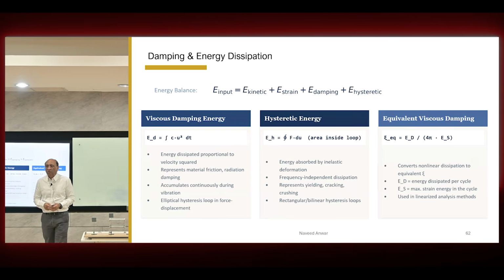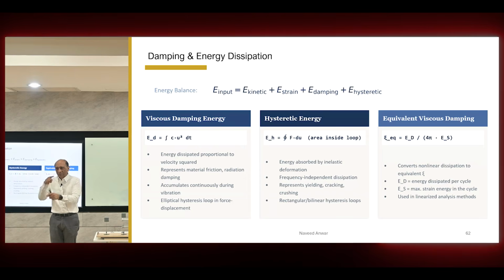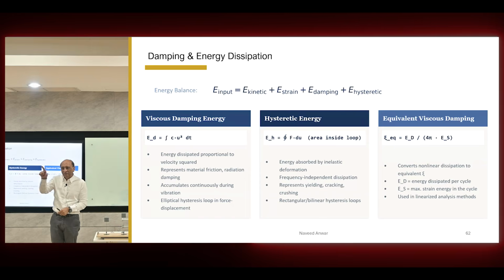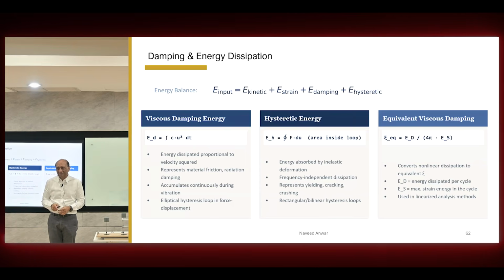Strain is just elastic strain, not hysteretic. You just bend something, it already has a damping because the material is just being compressed. So you take the stress-strain diagram, for example, and the area of the stress-strain divided by half will be the strain energy. Not about the damage, not about the loop. Hysteretic is when you complete one loop.